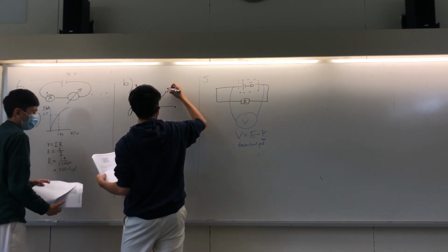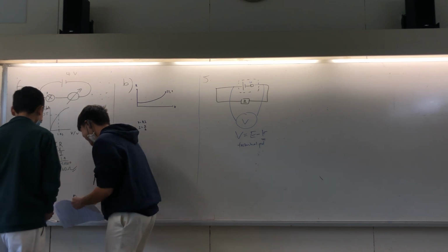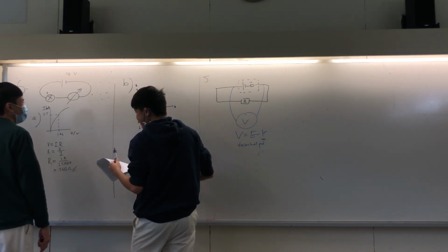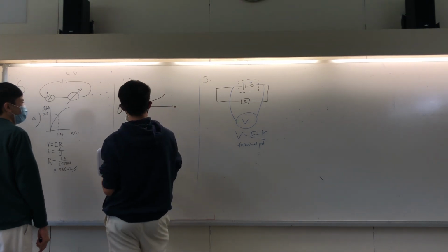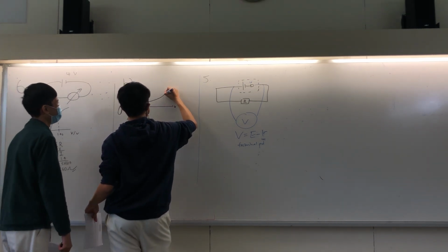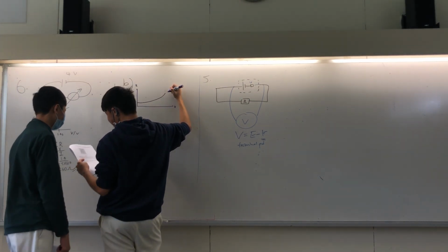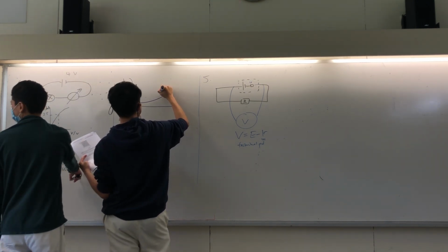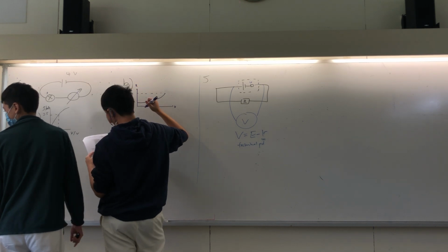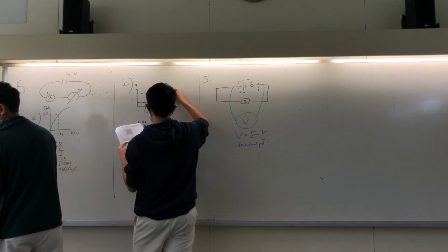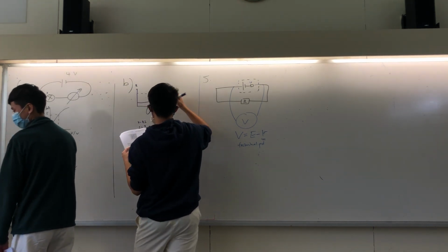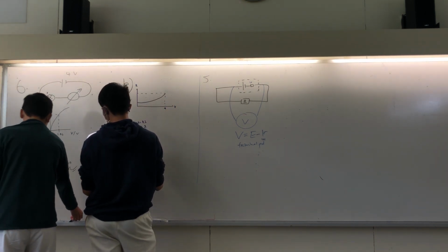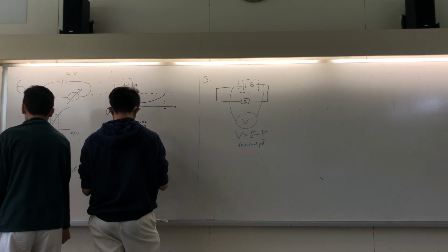So it's 1 volt over 1 milliamp. Like the right axis. Basically you are supposed to calculate the resistance at each voltage, calculate by V over I. That's the resistance of the lamp. We are not asked to find the resistance of the lamp.